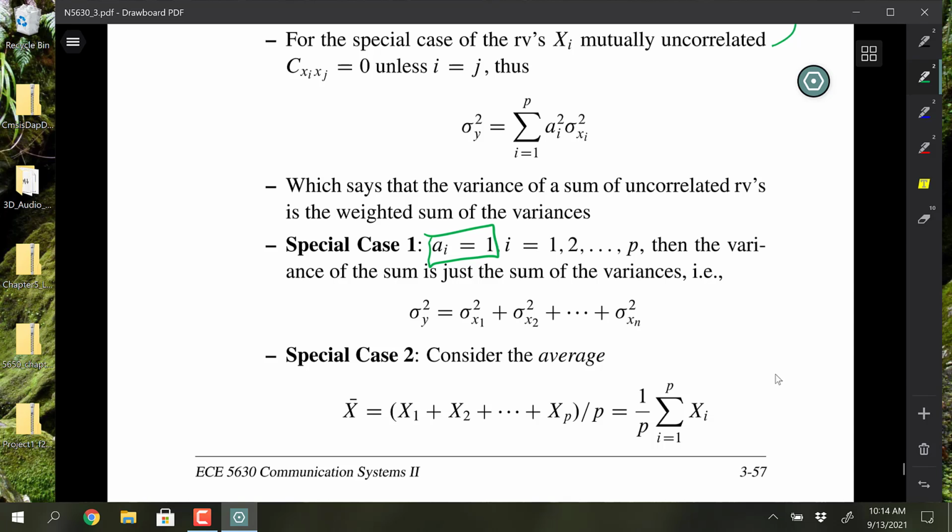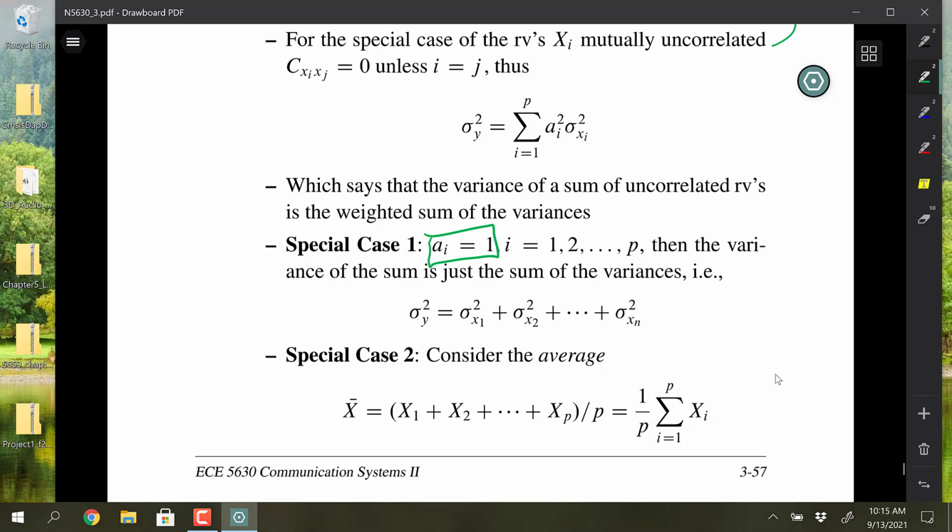So that was an inherent part of that project. The diversity combining wasn't going to be that hard, but it was how to actually ratio and then estimate. And one of the challenges in that is, signal to noise ratio estimation is noisy and imperfect. So the algorithm I chose was based on some papers I read using fourth moments. And the fourth moment algorithm works pretty well, but all algorithms fail if the signal to noise ratio gets too low. In other words, you'll be able to get a good estimate of the signal to noise ratio, but if it gets too close to zero, then things just start to kind of fail in general.